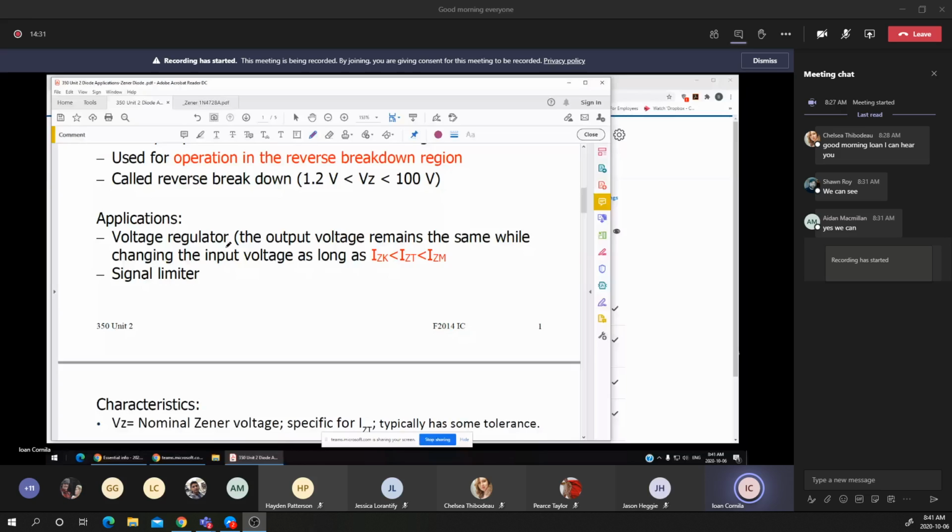We don't have to create another supply voltage, but one part of the circuit of the application you are making requires just 3 volts, or 6 volts, or 5 volts. What we can do is add a Zener diode that will lower the output voltage of the supplied voltage.